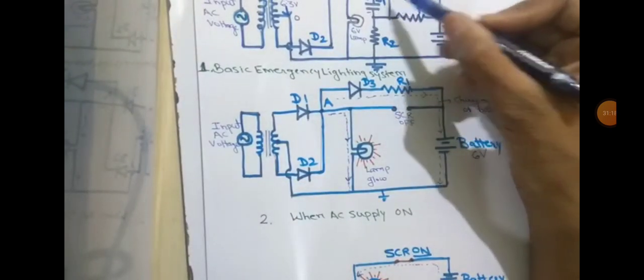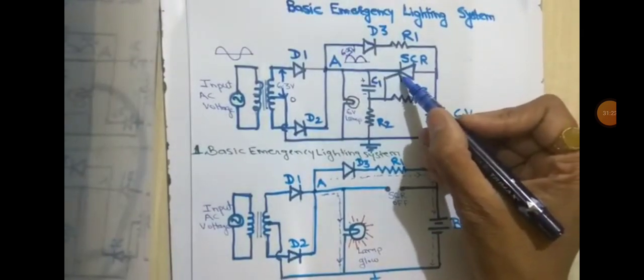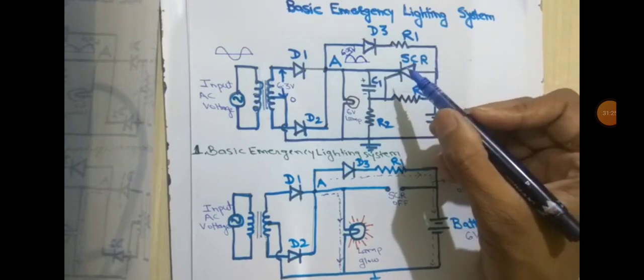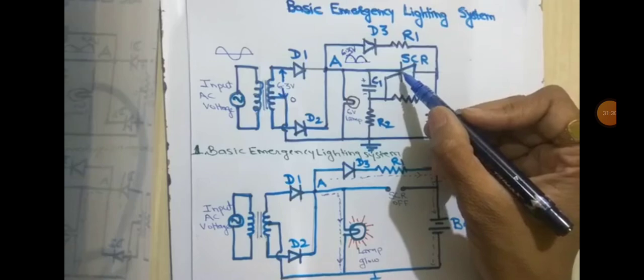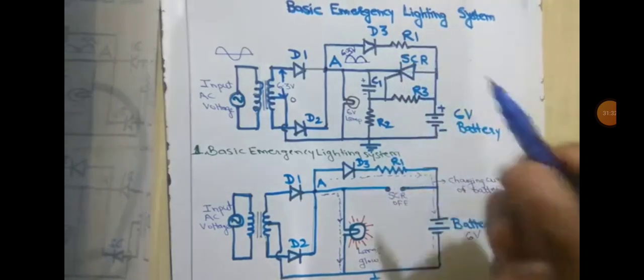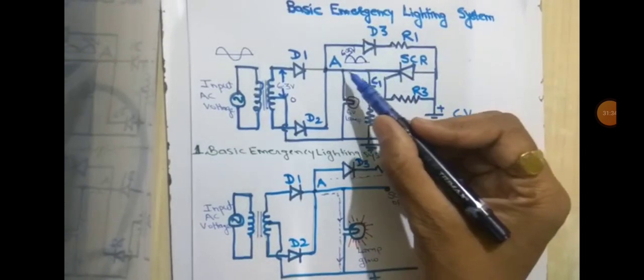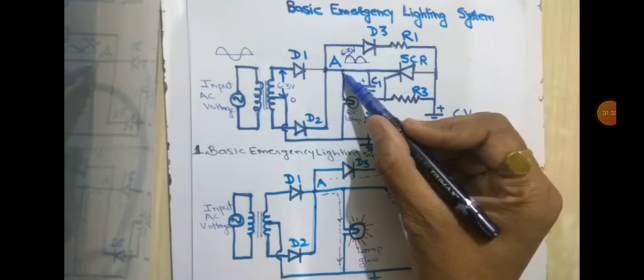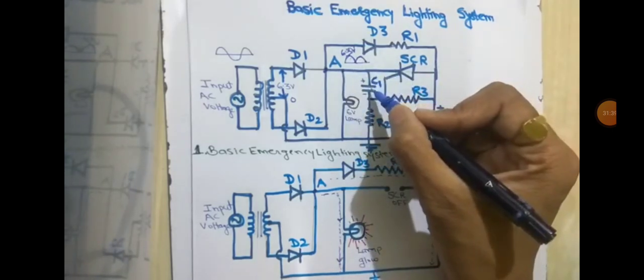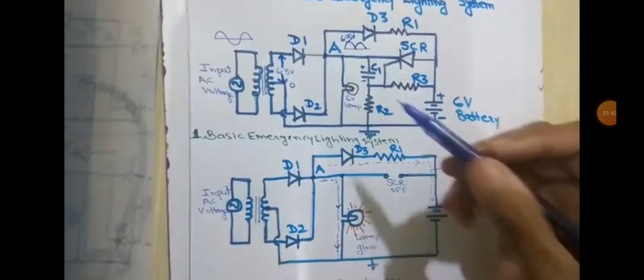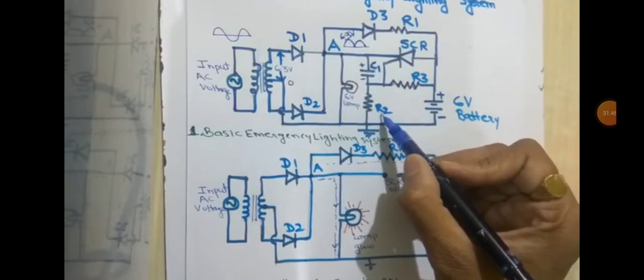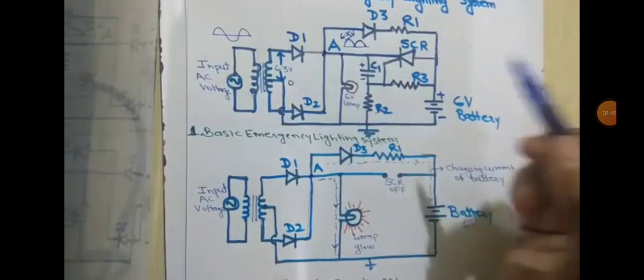Here the voltage at terminal A, which is connected directly to the cathode of the SCR, is a higher voltage than the anode voltage, and the cathode voltage is 6.3 volts. Because of this, terminal A has the maximum amplitude of the voltage. Capacitor C is charged with the upper plate positive and the lower plate negative. DC voltage is established across the resistor R2.